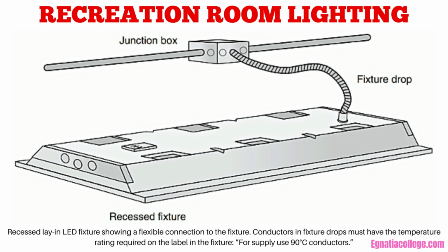Suspended fluorescent fixtures are intended for installation only in suspended ceilings where the acoustical tiles, lay-in panels, and suspended grid are not part of the actual building structure. The National Building Code and most electrical inspection departments require fixtures to be chained. This provides an independent means of support so, if the ceiling collapses, the fixtures remain supported. Canadian Standards Association (CSA) Standard C22.2E598 covers recessed and suspended ceiling fixtures in detail.